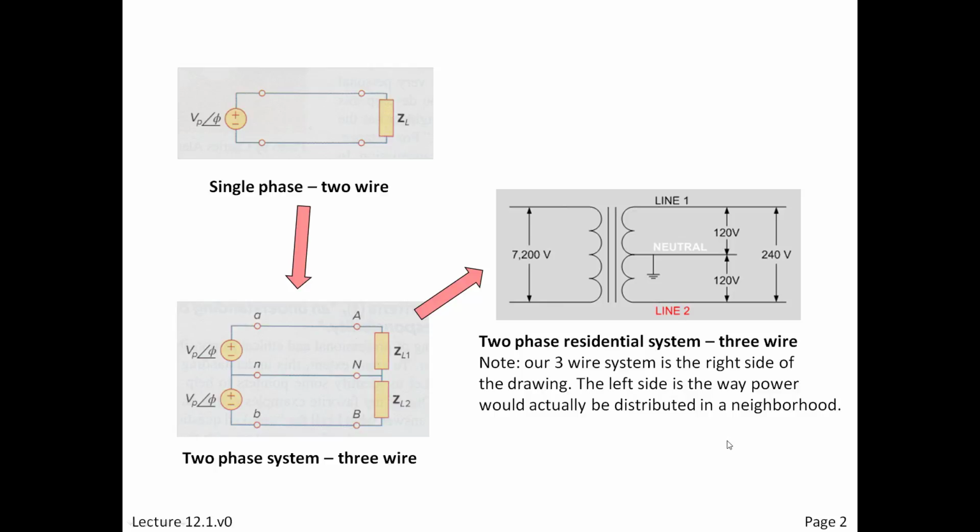If you take an oscilloscope and put it on your house lines, you can see this very thing. It's very important for this whole system to work in your house that this neutral line be a true physical line, but that it also remain firmly attached. This is shown as a ground, firmly attached both at the wires up on the pole and at the wire on this side in your breaker box.